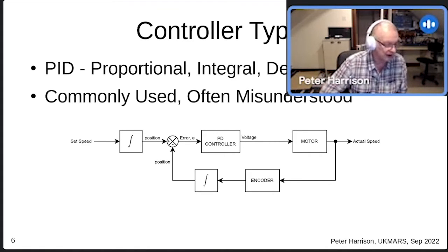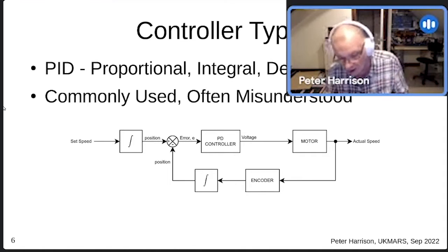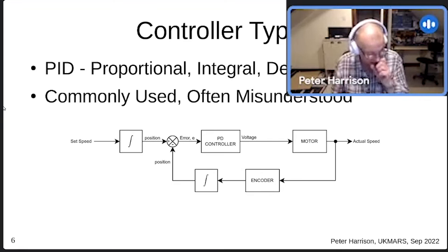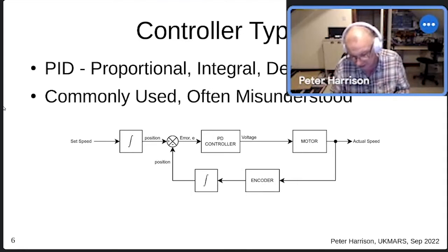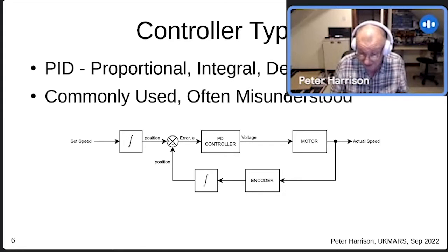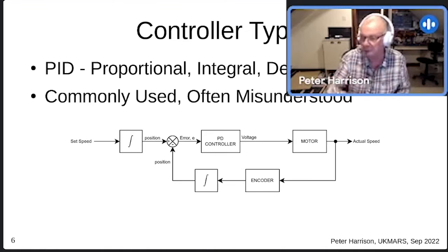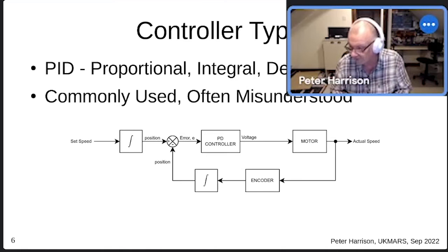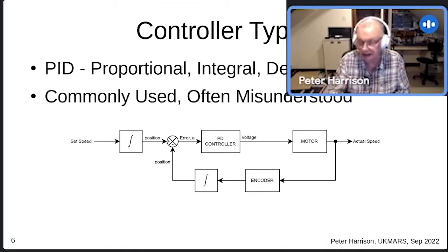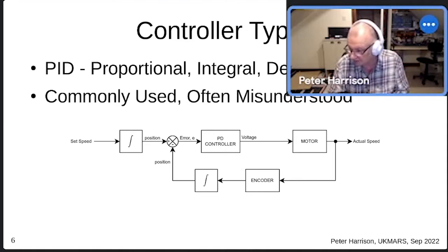So what happens is we have a demanded speed, and we know how often we're running the control loop, so 1/500th of a second. So if I want to go 500 millimeters per second, then in one control loop interval, that means my distance must move forward by 1 millimeter, right? And so I add a millimeter to the position.